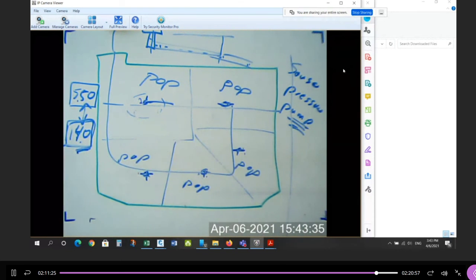And there's software to do it. You do not design the size of the water main directly. You really do what we did: we assume a size and then we analyze it. And if it doesn't work, then we change the pipe sizes, either up or down depending on the pressure.